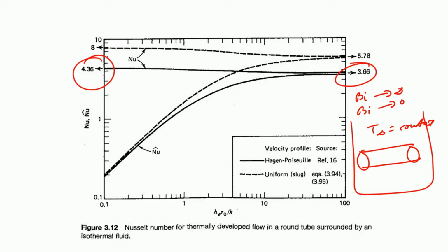So, this is what we call the duct side Nusselt number. Recall this graph is taken from Bejan, so the nomenclature is a little different. What Bejan uses as nu prime, I have used as nu, and instead of nu hat, which they have used, I have used nu in my derivation. So, there is a little bit of ambiguity between these two, but this nu is basically the duct side Nusselt number. So, just be a little careful when you look at and read the graphs.